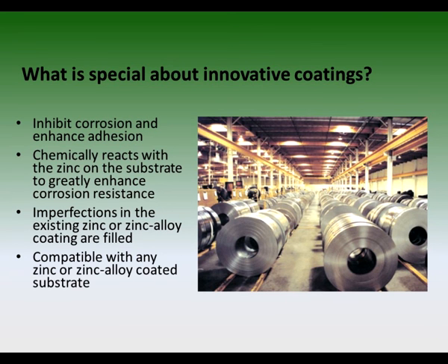The allowance for equivalent corrosion protection or alternatives to galvanized coatings created opportunity for the use of innovative coatings for CFS framing members. These coatings can be applied over an existing zinc-based coating to increase its corrosion resistance so that it meets the salt spray test requirements in ASTM A1003. In some ways, these coatings might even be thought of as an added protection, given that they react with and adhere to the existing coating. Imperfections in the original coating are covered up to make sure the entire surface is protected.